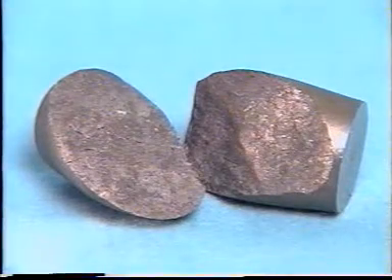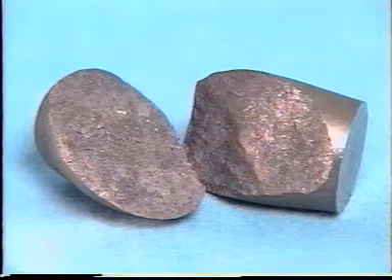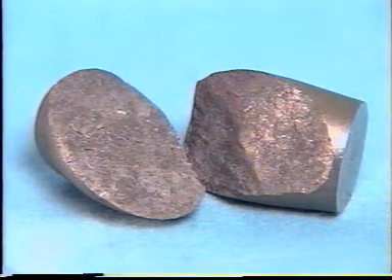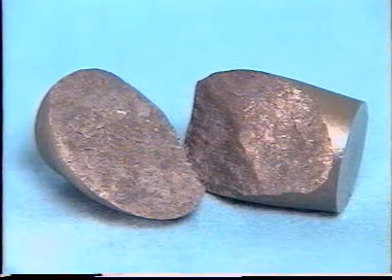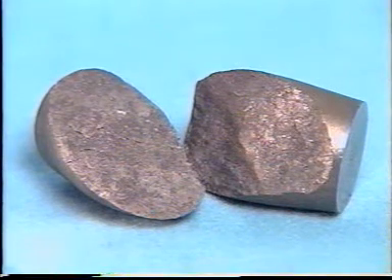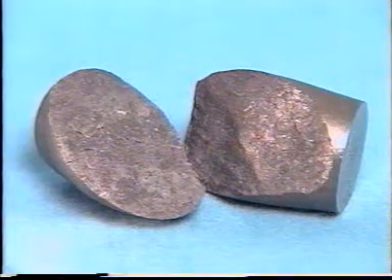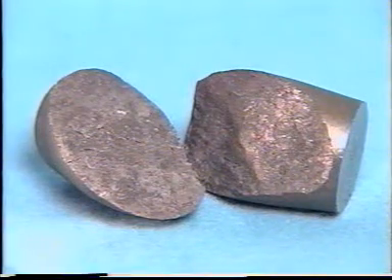A brittle material in pure torsion fractures perpendicular to the tensile stress component, exactly as it does in tension. But the tensile stress component is now at 45 degrees to the axis of the shaft. Thus, the fracture is spiral, providing the metal is brittle throughout its section.